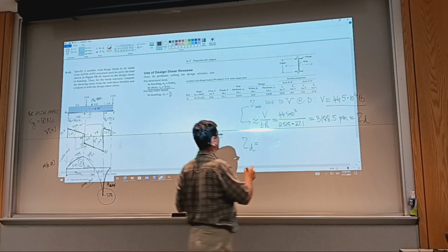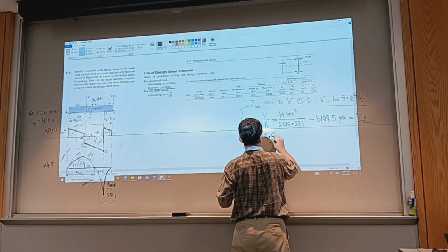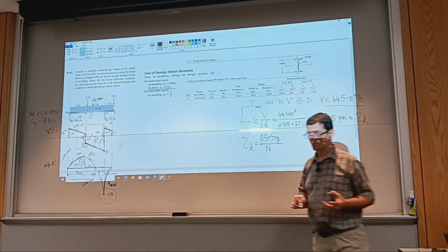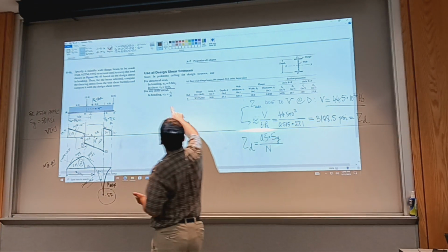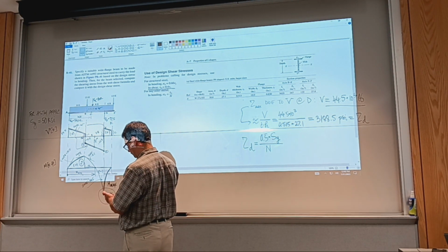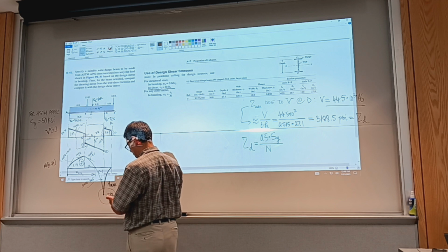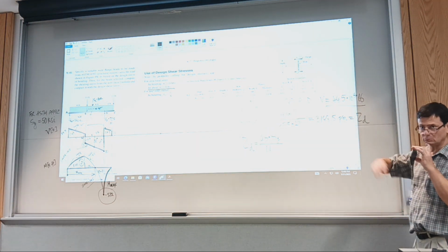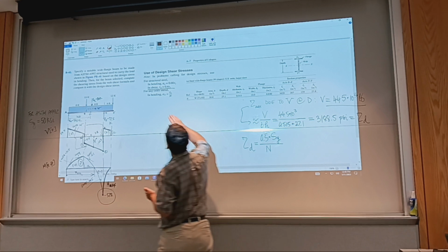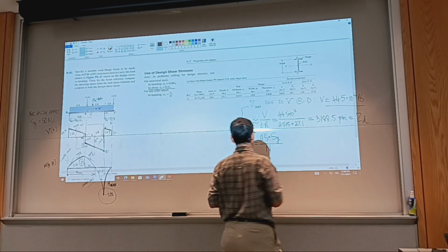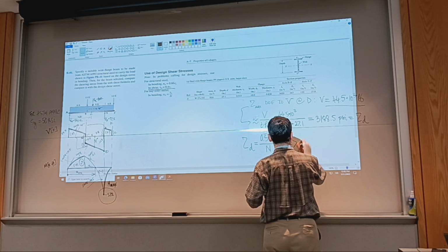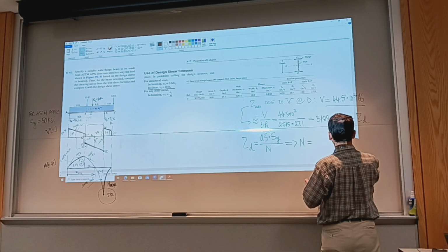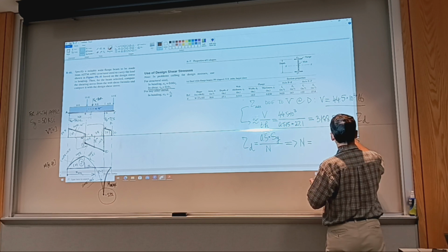Or we can say it's 0.5 yield strength in tension, an approximation of yield strength in shear, over the design factor. Based on this equation, the design factor was going to be 0.4. Take the inverse, divide by 2. That's 1.25. Is it clear? You can go to that one page where all equations for sizing, including structures, are. So we evaluate n, and we need to make sure that it is greater than or equal to 1.25.